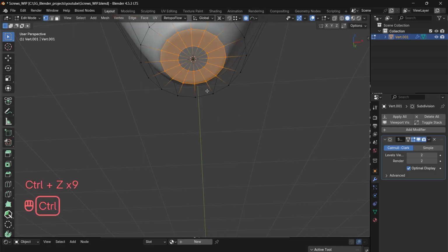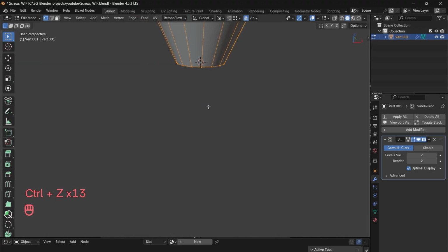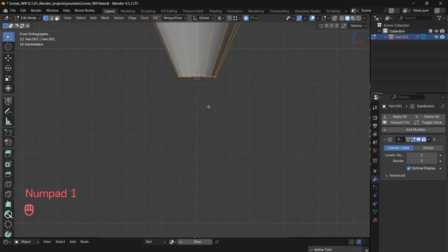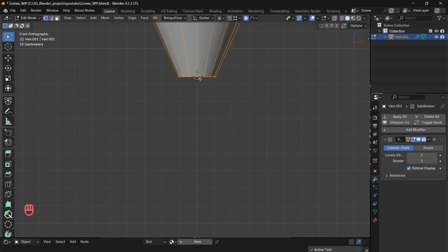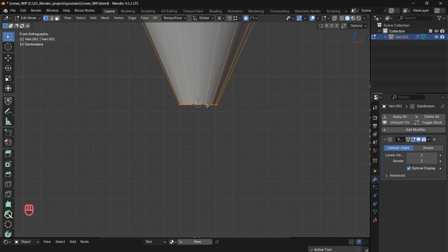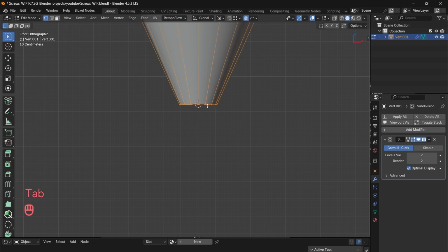So I will show you the right way to do it, so that even though it will create a sharp tip, it will have no artifact. Just follow along with me. Let me verify that my cursor is at the center of it. Yes, my cursor is at the point where I want. I will tab out of it, and before doing that, let me verify the number of vertices there. I see there are 16 vertices.